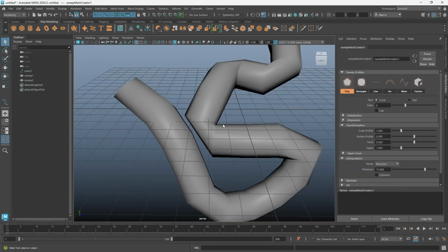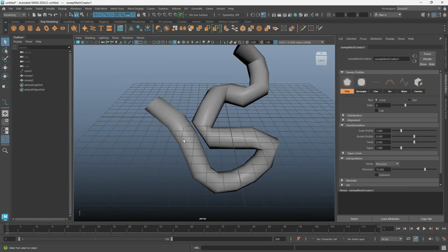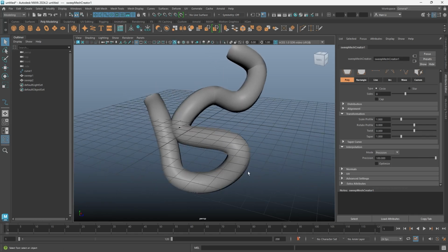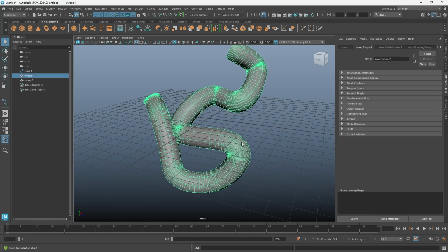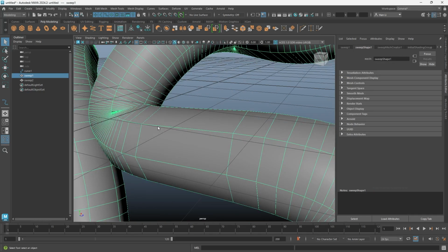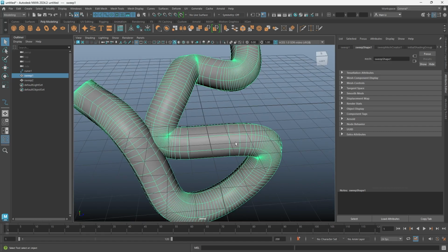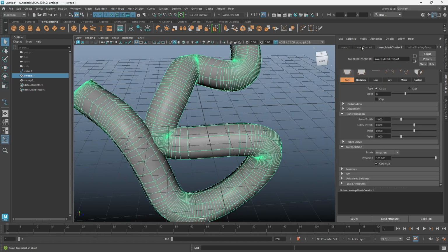You can see here how it's not very good because there are a lot of jagged edges and that type of thing. It's not fully conforming to the mesh. That's because in this interpolation area over here, it's only at 75% accuracy. If I increase this all the way up to 100, it follows the mesh perfectly. And then click optimize as well, just so I have fewer of these straight edges, these, what's it called, edge loops initially.